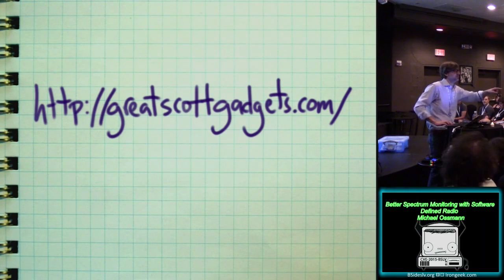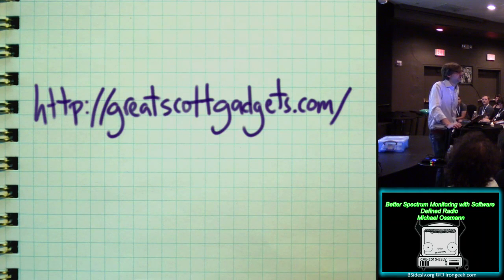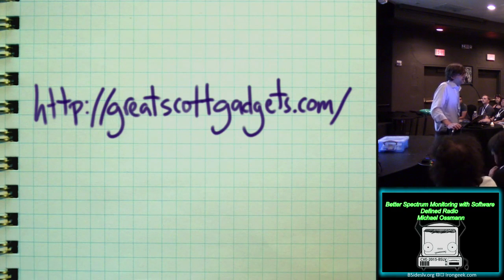We had some really good questions so far. When you eliminate USB as the rate limiting factor, what are you running into that's limiting the tuning time? Yeah. The question is, if we eliminate USB from the tuning time, what is the limiting factor? Why does it take any time at all to tune? And yes, it is primarily the PLL lock time of the frequency synthesizer that is producing the signal.